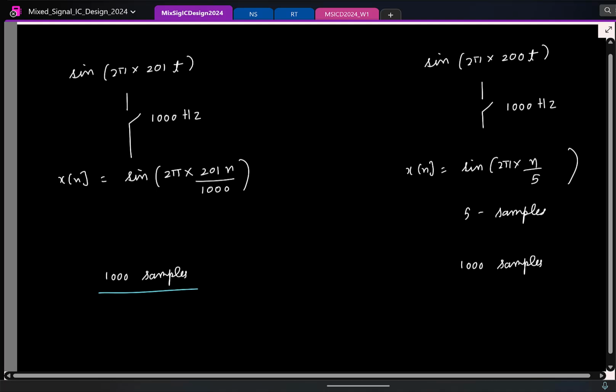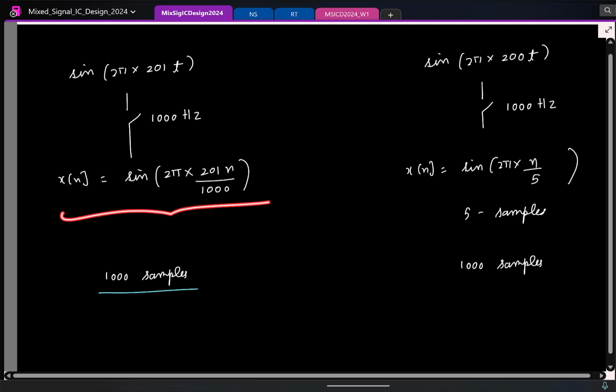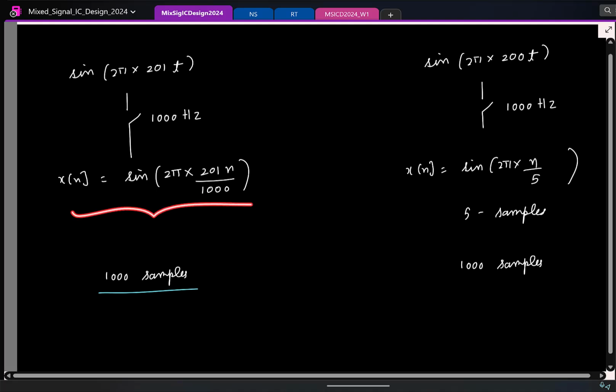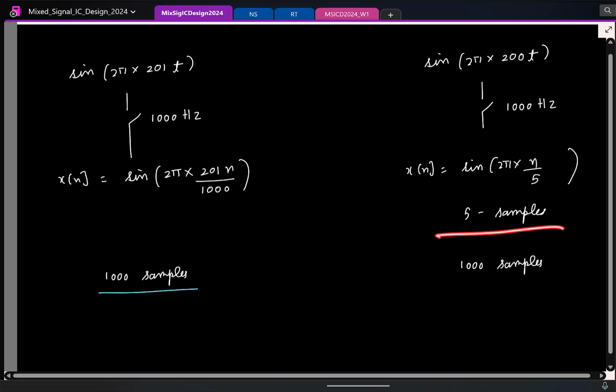Right? So in the first case, when I took the signal, quantized it, and took 1000 samples of the quantized data, all the 1000 samples that were fed to the quantizer were unique, because the signal repeats only after 1000 samples. If I take any set of 1000 samples continuously, it's going to be all unique, right? Whereas here, although I take 1000 samples and quantize it, how many of them are distinct?